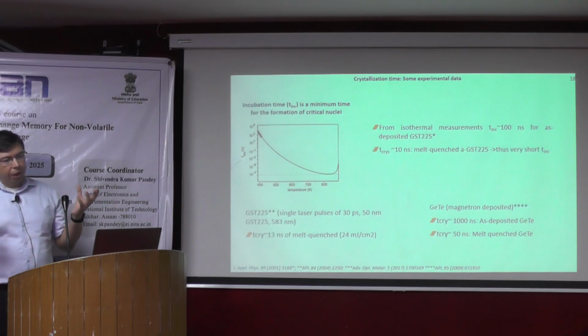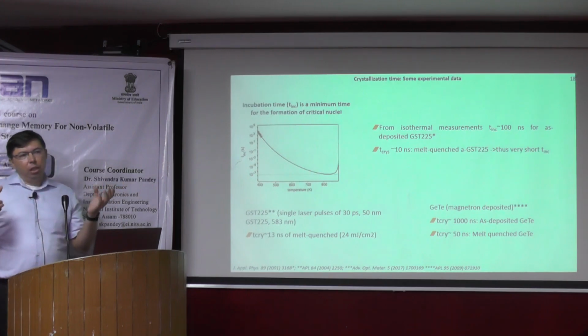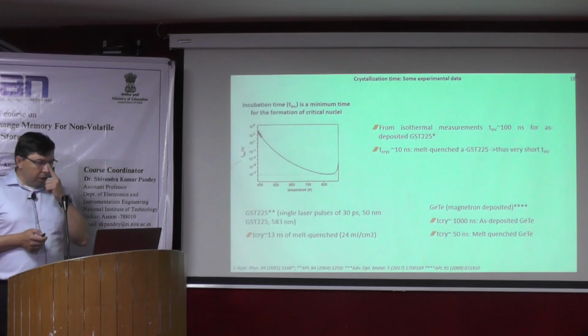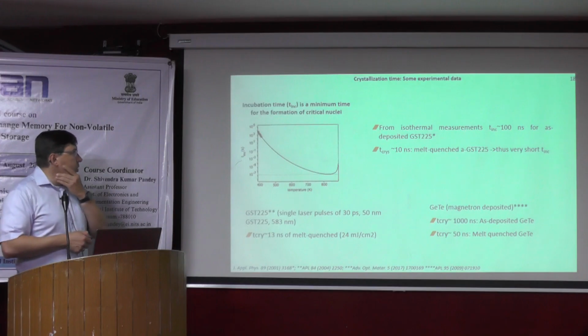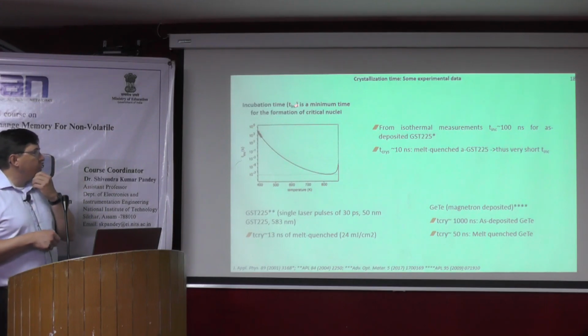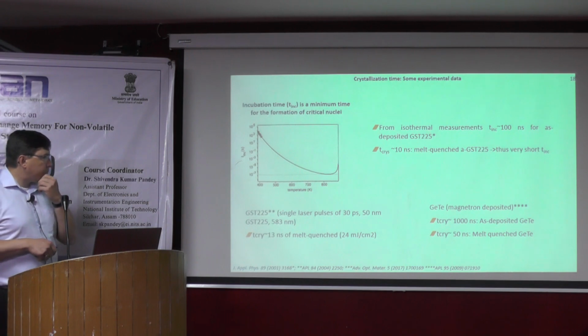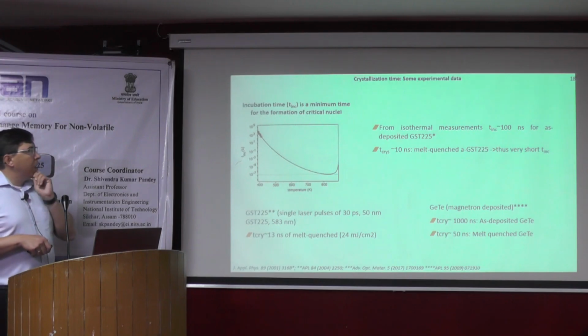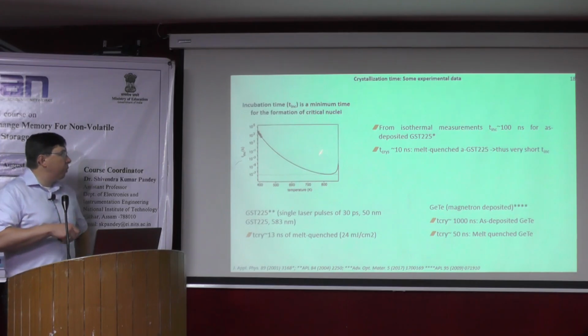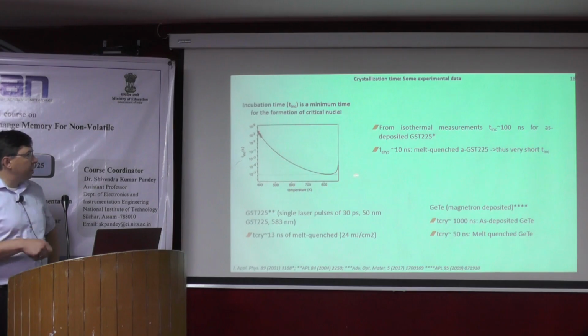We saw already that there is a structural difference of these states, but there is also a difference in the crystallization kinetics of both states in the sense of the time of critical nucleus formation. There are also some basics for the critical nucleus formation. Of course, this nucleus formation depends on the temperature. If we increase the temperature, we need less time to form this stable nucleus.